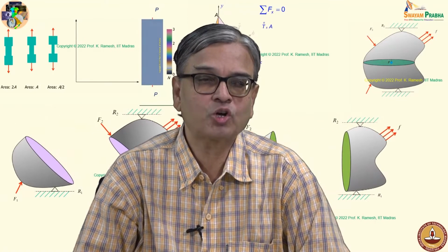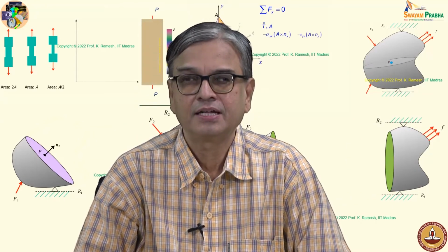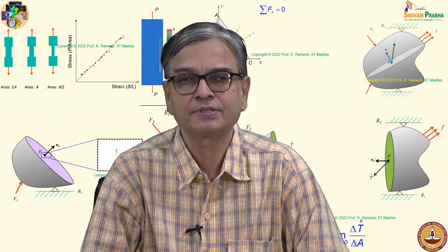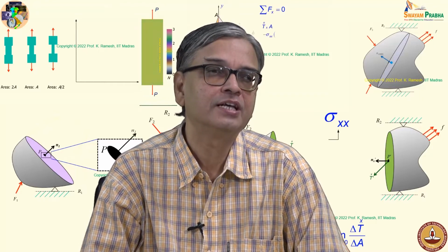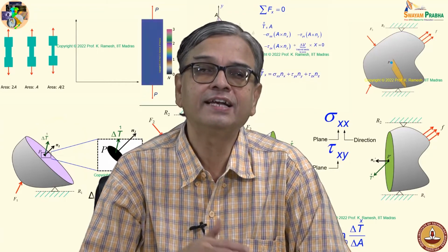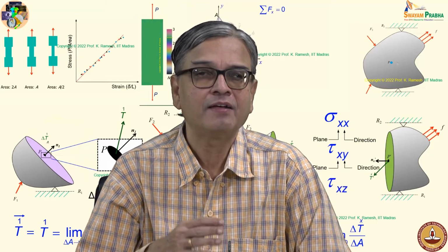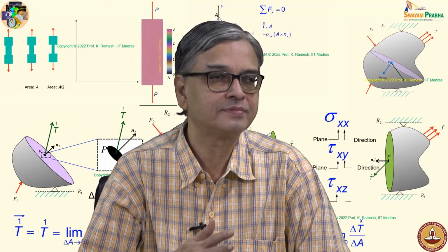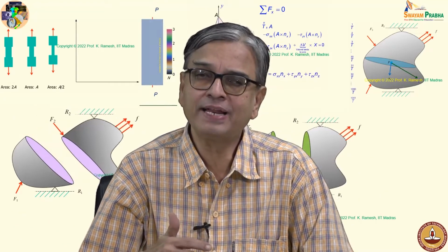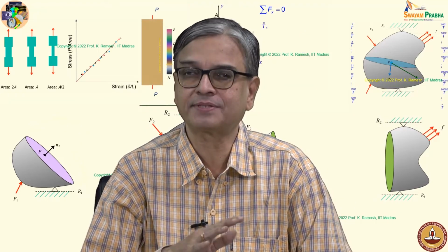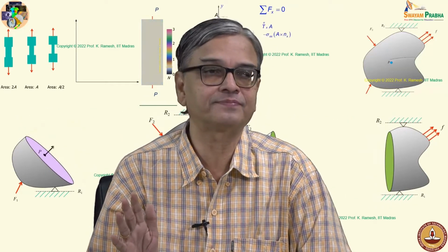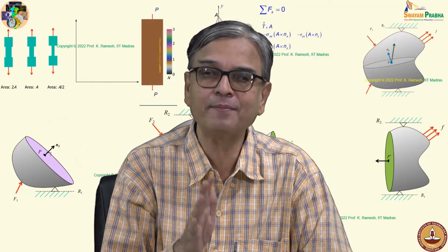Let us develop concepts related to stress. These will be used in this course as well as in your future courses and also in advanced studies. Even though in this course we will confine our analysis to slender members, in the development of concepts of stress, we will start with a three-dimensional body. And it is also not restricted to isotropic materials. In fact, we will not bring in the material aspect at all while developing the concept. Only one aspect we will say is, we consider this as an elastic continuum. That is the only thing that we require for a mathematical development.